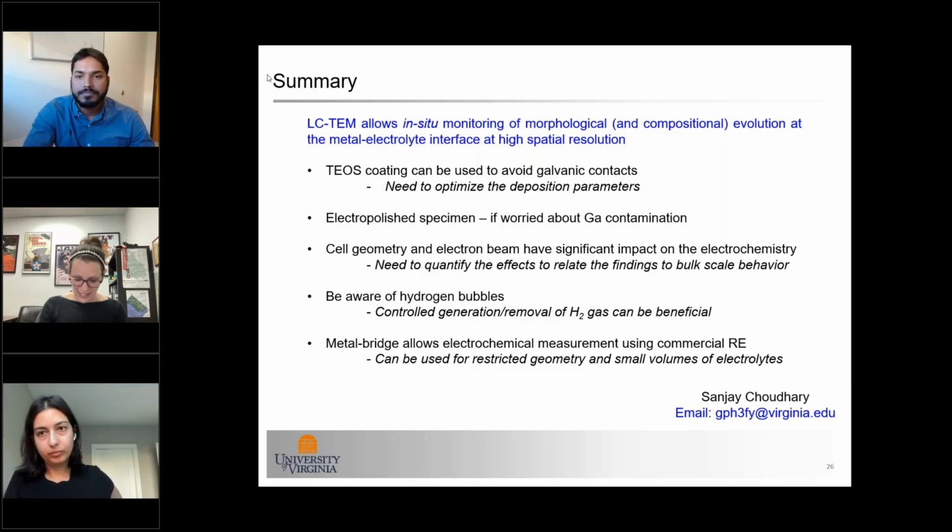And then this last question right here, and you may have touched a little bit on it at the end, but maybe there's some elaboration. The TEOS coating, what's the material that is going down, and does it have any effect with your electrolyte? So it is silicon oxide, which gets deposited, and then a volatile gas gets evaporated. We consider silicon oxide as an insulating or non-conducting material.